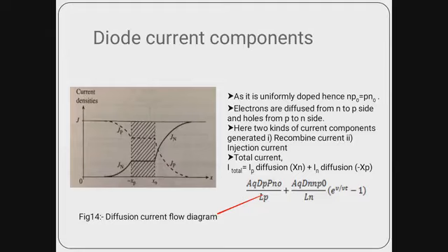So what is exactly happening over here? The whole current, the holes here would be exactly equal to the electron current which is coming from negative to positive terminals. Both are equal because this is a uniformly doped material, a uniformly doped PN junction diode. So the number of holes flowing in at this point would be equal to the number of holes required to recombine with injected electrons, to the number of holes injected into the depletion region.